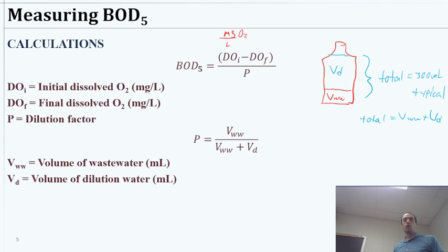We're going to be dealing with volumes here in milliliters pretty much always. It's just kind of going to be our standard with the BOD. Of course, the concentrations are milligrams per liter. So we've got liters there. We shouldn't ever really have to convert between the two, because it's the concentration units versus the volume of the vessel. Okay, so I'm going to leave it there. We'll get into slightly more complicated BOD stuff next time, and start into the modeling of it downstream next time.